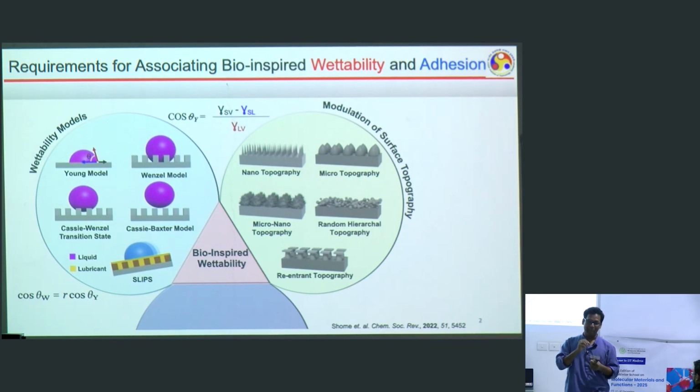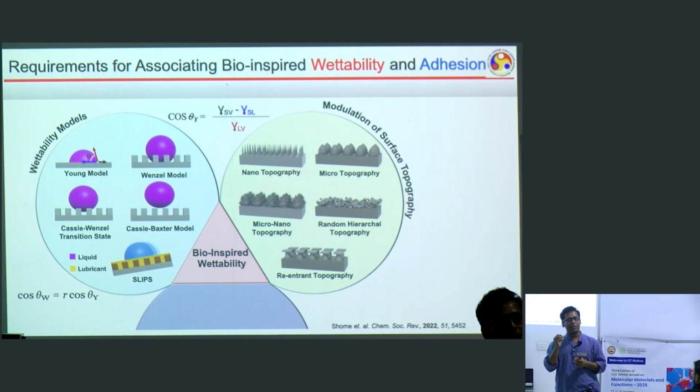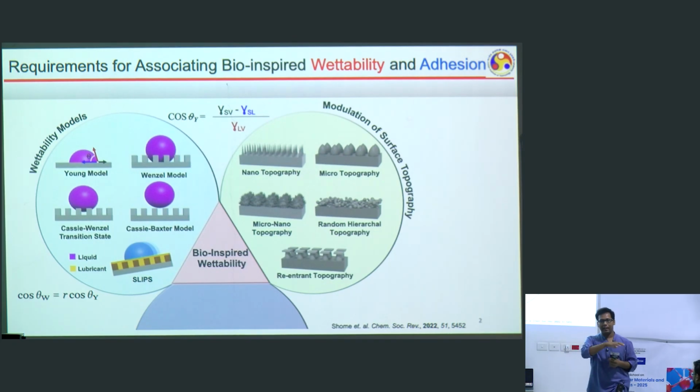It's basically for super hydrophobic interfaces like the lotus leaf. Entrapped air in very rough interfaces, or interfaces which have a dual degree of roughness, I'll talk about that in a little more detail. There in the grooves, there is entrapped air which minimizes the contact between the liquid and solid interface. Because of that, you see this heterogeneous liquid wettability and extreme repellence.